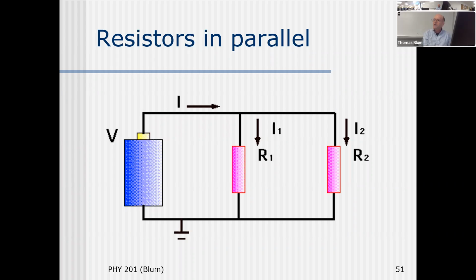If you see a connection wire, it doesn't mean in this picture they are geometrically parallel. That does not matter. It has nothing to do with it. Electronics is about connections. If R2 were going horizontally up here, they would still be in parallel. It's about the connections, not about them being visually parallel. I will try to trick you someday and put it over here. If you understand that parallel in a circuit means there's a wire connection on one side and a wire connection on the other side, you will never be fooled.